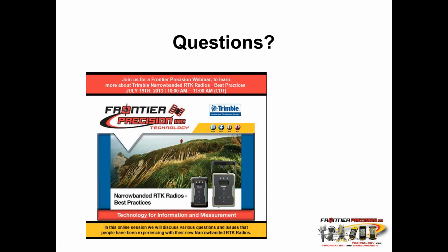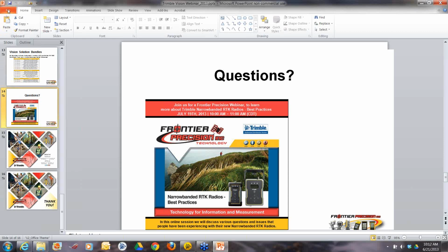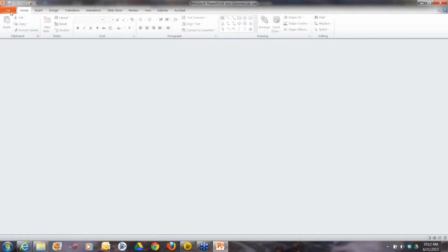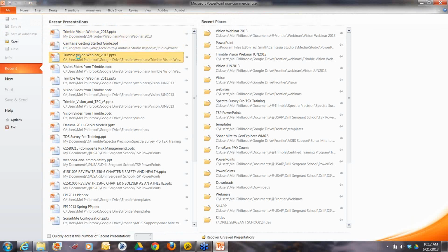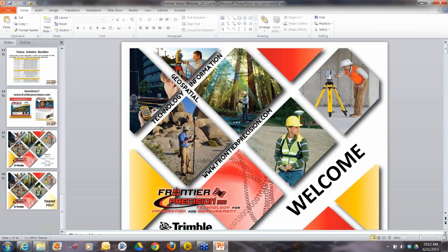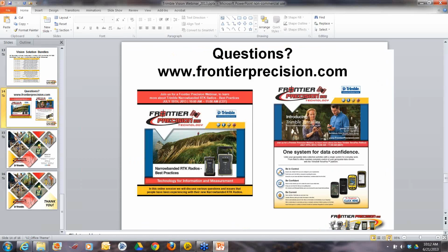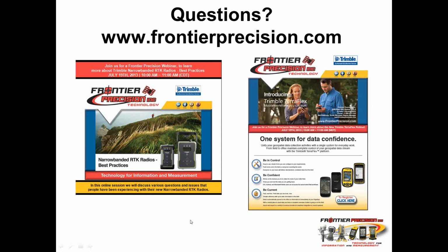No, I want you to do it because I'm not sure I understand what he's asking. So a photo, assuming this is when you were clipping out an image to put on your controller. You were stressing the importance of having the world file, and that world file needs to be in your coordinate system of choice. So my assumption is that you make sure your project is set up in UTM and in meters, and then import the image that you're going to clip out, and then you can change your coordinate system. Is that right?